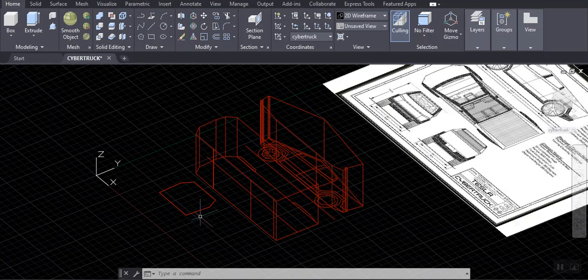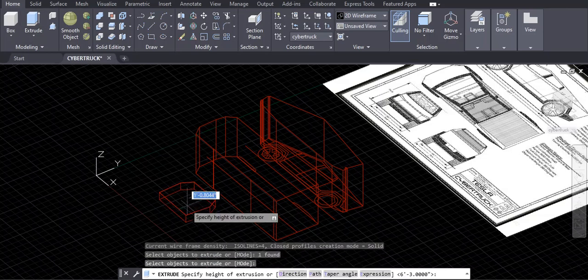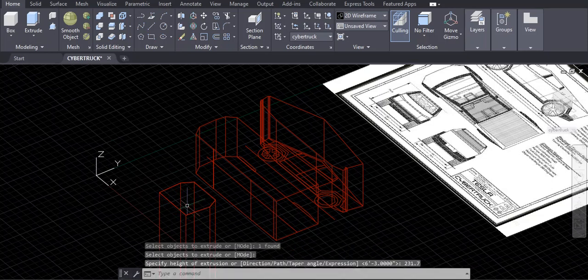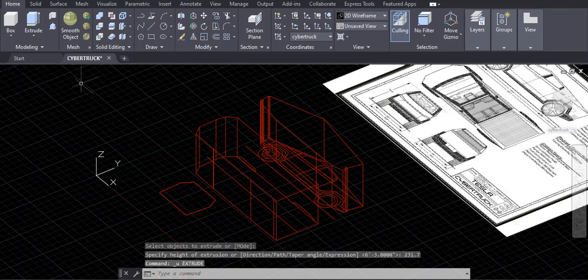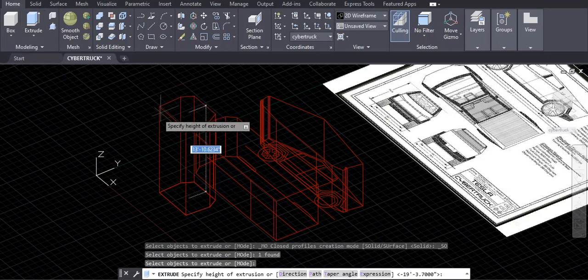And how about the front view? Again, enter, extrusion comes back, select the front view, enter. Now, that is a long line on 231.7. Okay, so 231.7. All right, I can Control Z this and do it again. Extrude, enter, and 231.7. Enter.